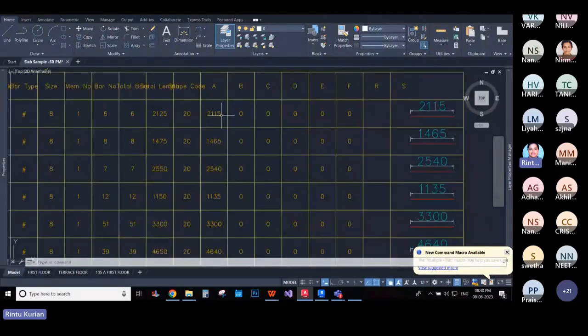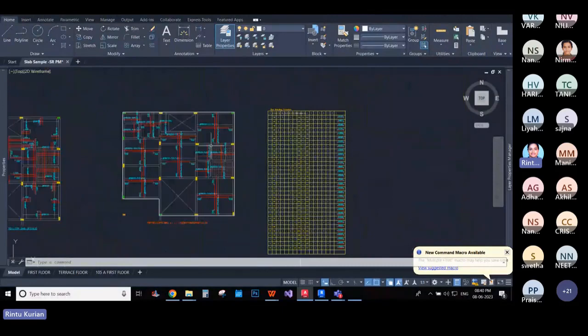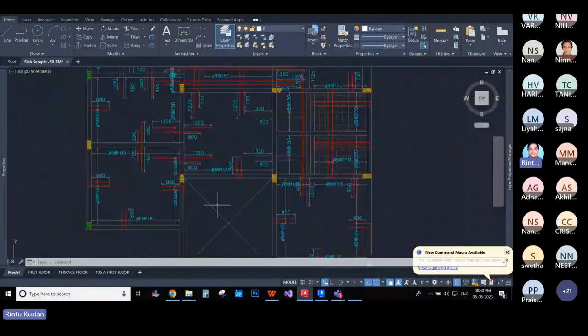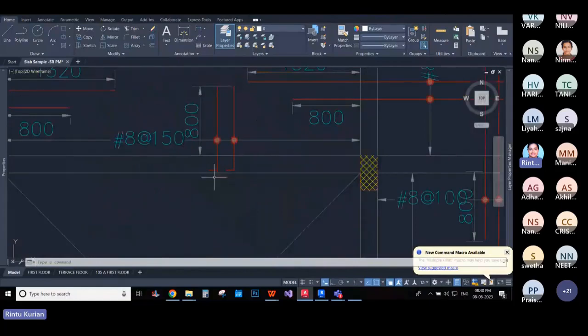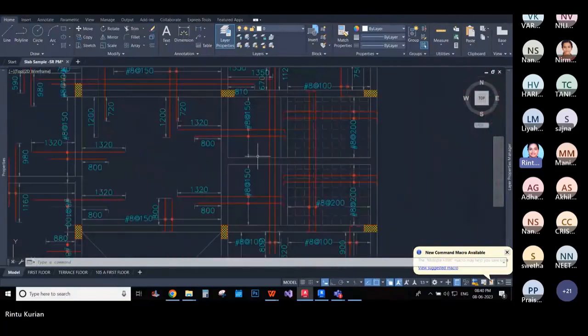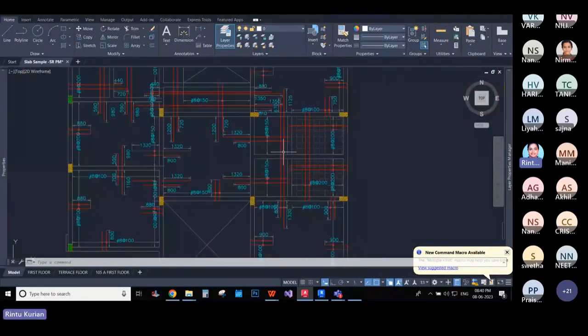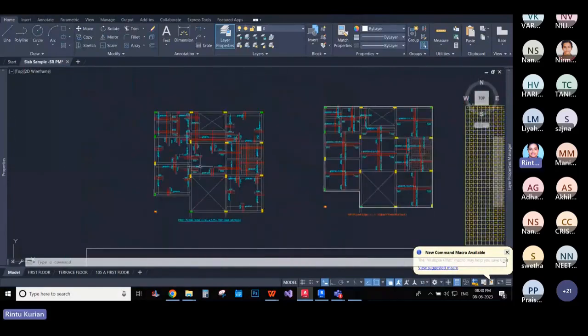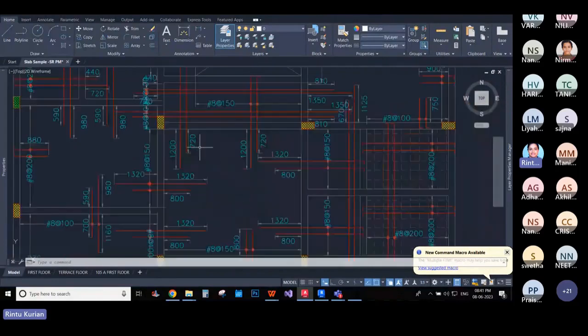Okay. Now, if I am scanning the other one, it will be different because there are L-shaped bars and straight bars. It's a mixture of these two different types. And usually in slabs, we just have 3 types of bars used: the straight line bars, the L-shaped bars, and U-shaped bars as you see here. So all these 3 types are mainly used. Deviations are found rarely.